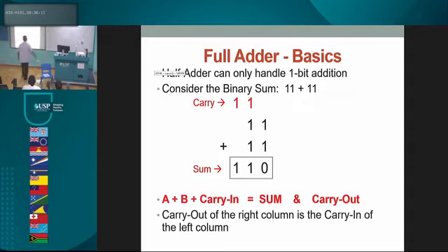I don't want to use the word carry because in our system we have something called carry, right? So in a half adder, our sum only had the capacity for 1 bit, and the carry was another bit. Sometimes carry would become overflow. As your system becomes larger, if you want to do a real sum, like 5 plus 5, that's 101 plus 101. The answer is 1010. How do we implement that in a circuit? You've got to think about how many bits can be carried, how many bits can be held, how many bits you need to process. So you make your system as large as possible to cater for that.